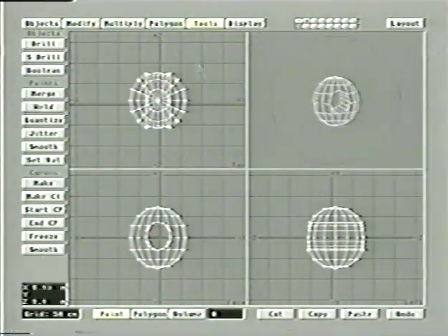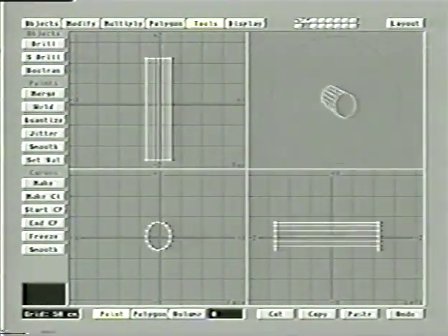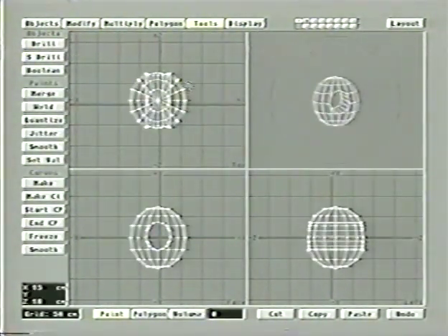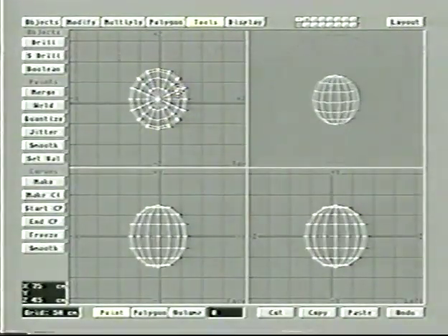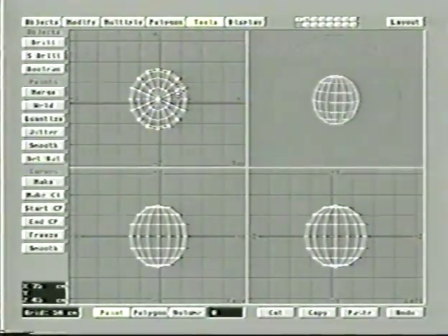It just doesn't get rid of it. It's still on layer 2, unaltered. But we can still see it in black because it does not automatically turn off the inactive layer when you do a Boolean. So here's a subtract, fairly simple operation. Let me just undo that for a second to go back to our regular sphere and show you one other just quick use for subtract so you see the idea. In this case, we pulled the disk straight through the sphere.